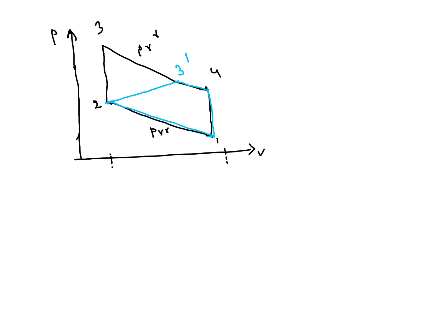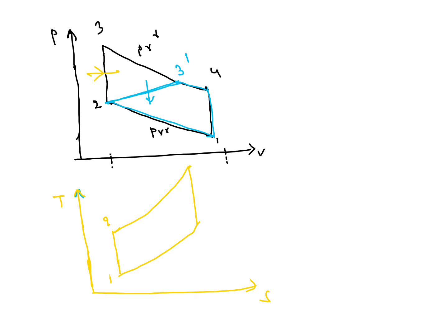Here pressure is constant from 2 to 3 dash. Constant pressure heat addition. This is also important. In Otto cycle, constant volume heat addition. So many times they ask this question also. Otto cycle, constant volume heat addition. Diesel cycle, constant pressure heat addition. And in the TS diagram, for the Otto cycle, 1, 2, 3, 4, volume is constant here, also volume is constant.